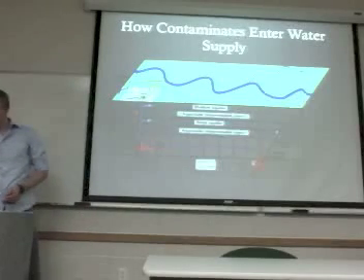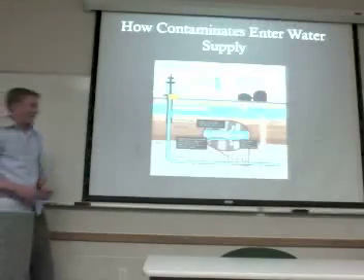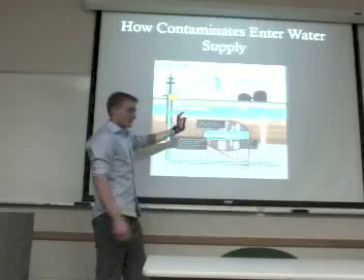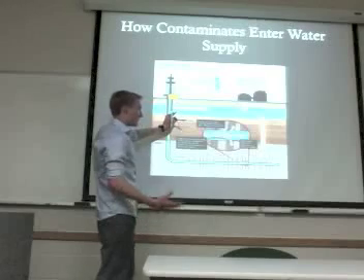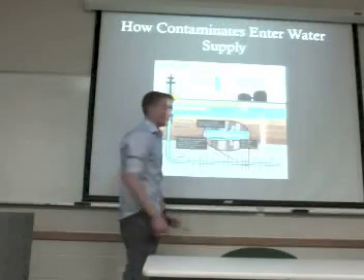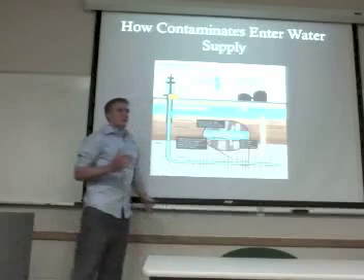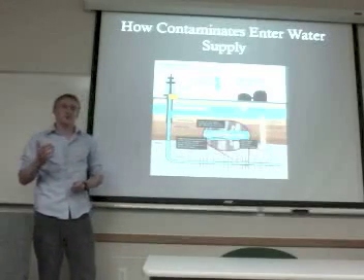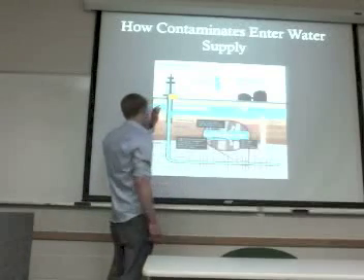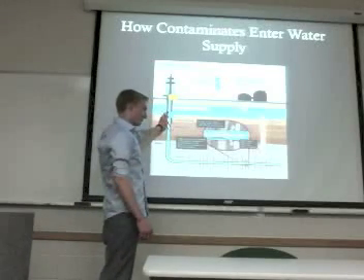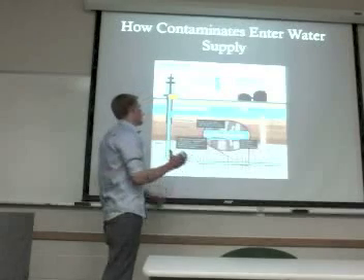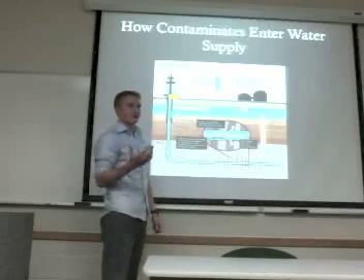The biggest danger, by far, is the first 100 to 500 feet. This is where most of your underground water wells, your water tables, and the upper aquifers are. So oil and gas companies try to add in 2 barriers of protection. They first encase the drilling borehole in steel, and then they encase it with a second layer of concrete.